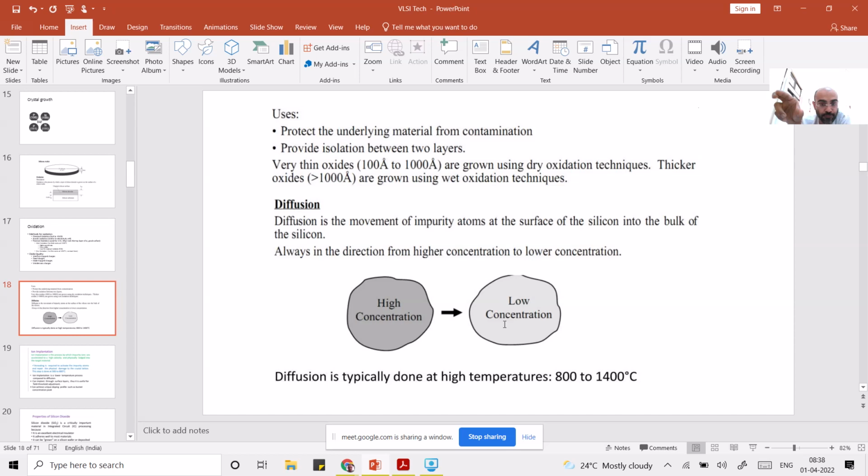That is the reason why, when we were showing the diagrams in the very first unit, I showed you that the source and the drain regions were under the gate region. Some of the gate is over the source and the drain region. So there was some overlapping, and because of that some capacitance comes into the picture. The oxide related capacitance which we have studied earlier is because of that only. So this diffusion is not very perfect.